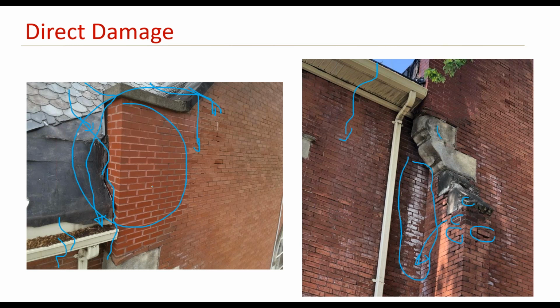One important thing to mention here also, that's a heritage building. So whatever they did with the restoration here, they used a newer material here that is not compatible with the old material. And again, this would create cracks and would put some stress on the old material that is usually weaker. So it's really important when dealing with historic buildings to choose a heritage specialist or a historic restoration contractor.